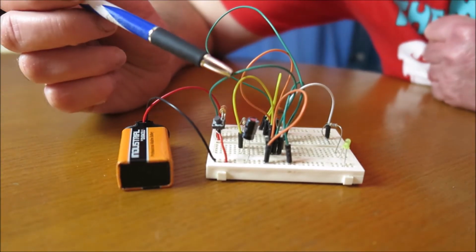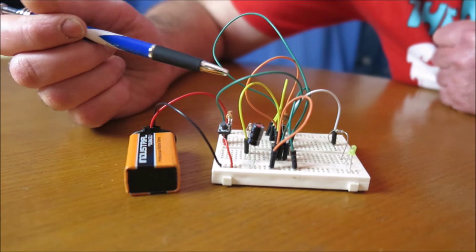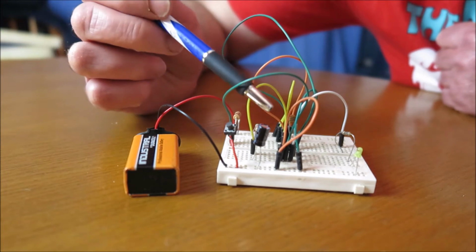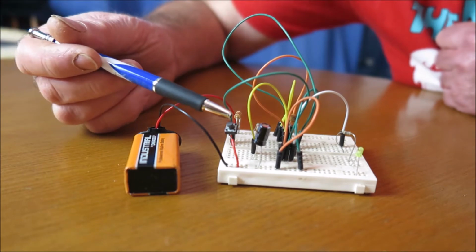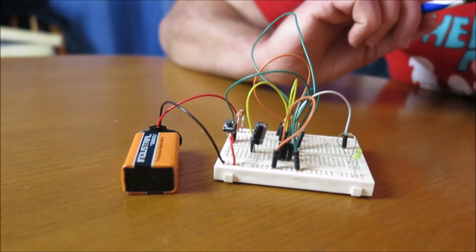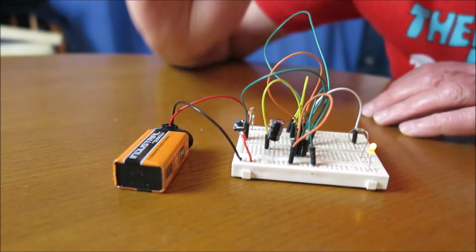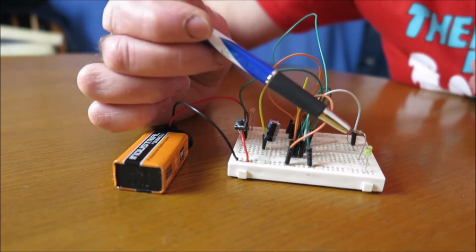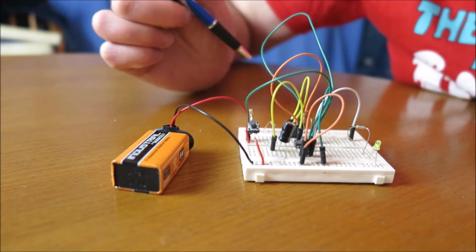This is the circuit. Once again we're using the 555 timer chip. Now we've got a little switch here, and what's very important is this capacitor and this resistor. So once again we're using these two components for timing, and we'll do a little calculation on that later. But if I operate this switch here, what we'll see is the LED light up and stay on for a period of time after I release the switch. So we pulse the switch and then we have the LED coming on. And the length of time that that stays on is dependent on the capacitor resistor combination.